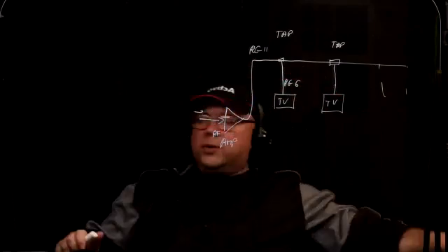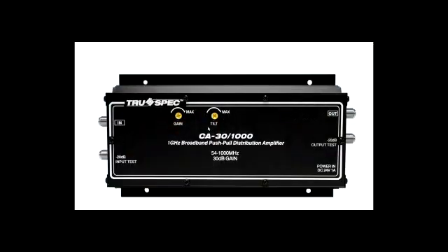So that's why when you adjust the controls of the RF amplifier, you have to have a good balance between the gain of the whole system and the slope of the whole system. So you have the input, you have the output of the amplifier, and over here you have a minus 20 dB test signal, so you could just connect your control television set to see what's going in. And here you can just grab a minus 20 dB test signal on the output just to see what's coming out of the amplifier. Right?